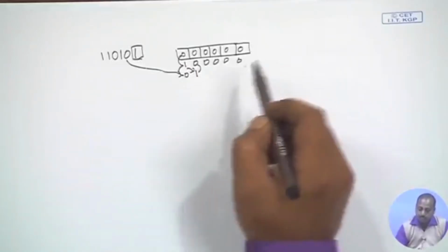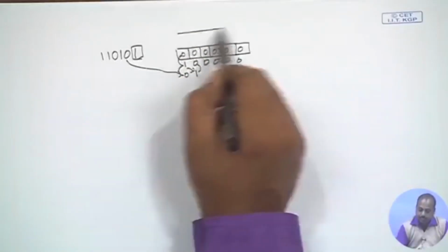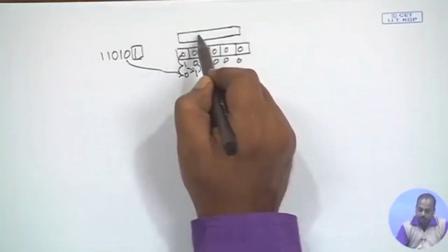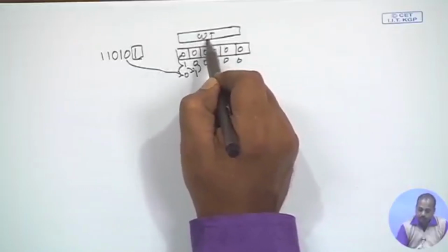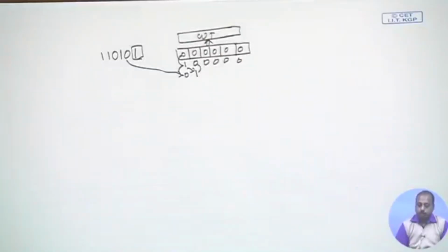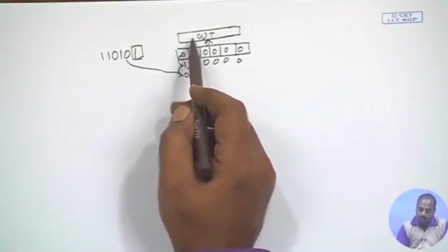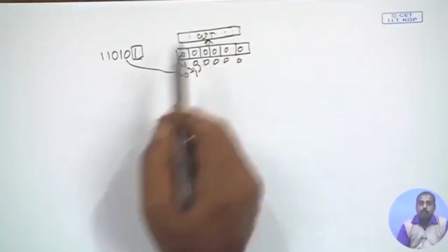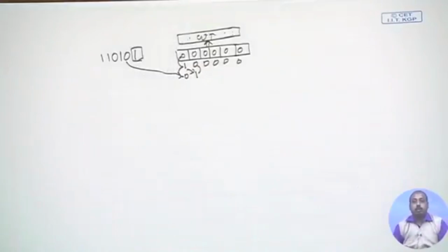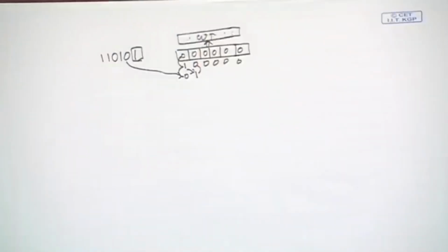Now, ideally what is required is that this scan chain output will be fed to the circuit. So, they are connected to the inputs to the circuit. For every transition that occurs, I need to compute the total number of transitions in all these gates. So, I need to do a logic simulation of this circuit for every shift that I do, which is a very cumbersome thing. It is a very complex computation, and the overhead of computation will be very large.